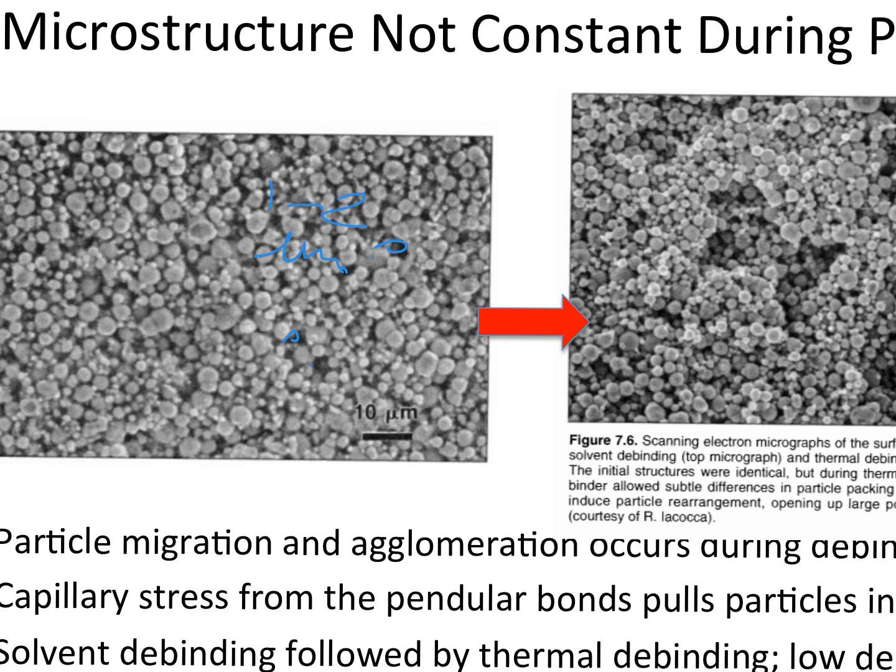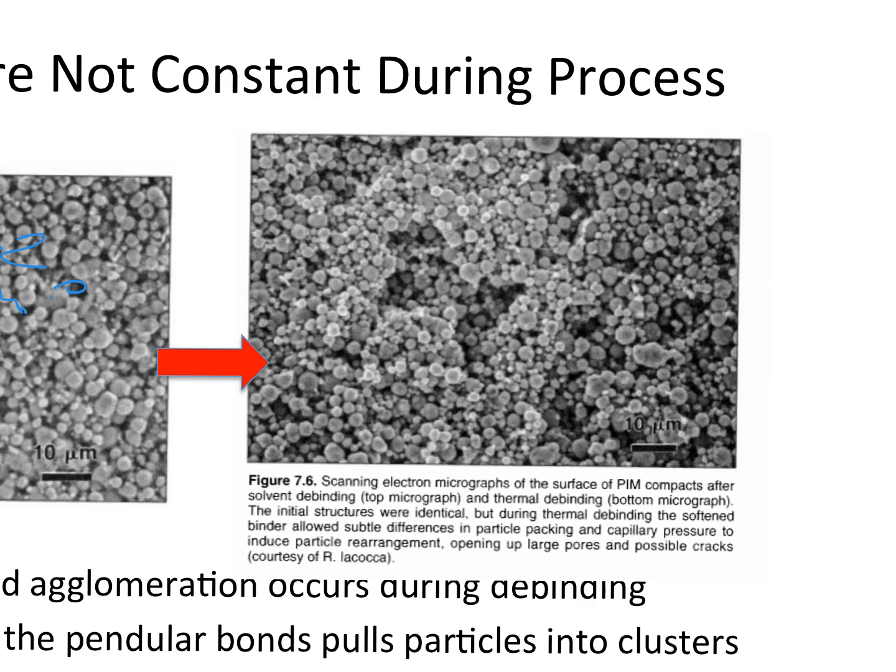But what happens is we heat this up, and all that liquid starts to move around prior to volatilizing out. And when it moves around, it moves the microstructure around too. It pulls particles together. So this is the biggest example. It's whatever that is, a 50, 60 micron pore that wasn't there in the left-hand microstructure. So the left hand, with inappropriate levels of heating, for example, would lead to the right hand.